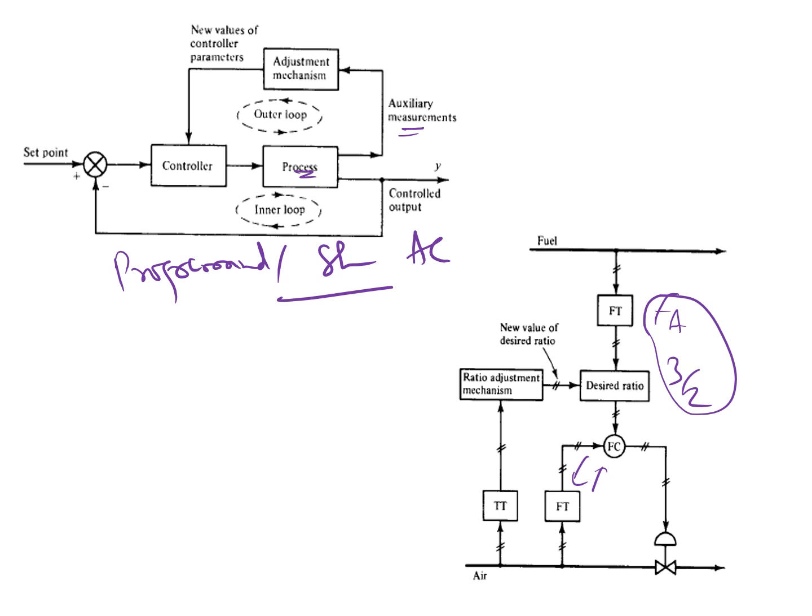So what we do is, instead of measuring the flow rate, take the temperature of the air. That is your auxiliary measurement. Because this is fuel to air ratio, fuel is not under control, so this is called a wild stream. Air is under control. Flow rate we are already measuring for this, but we have to take an auxiliary measurement, which is not for this controller section. So take one more variable.